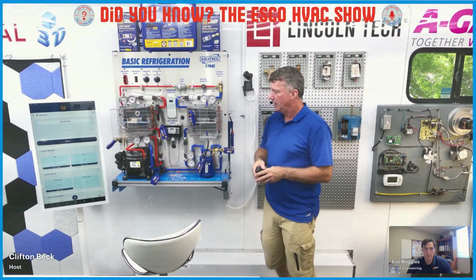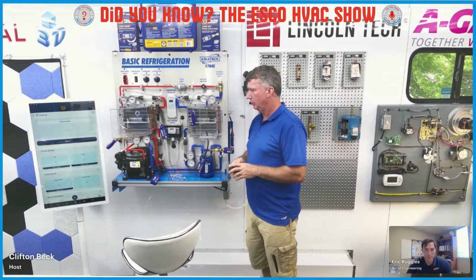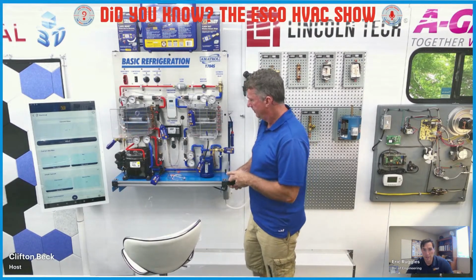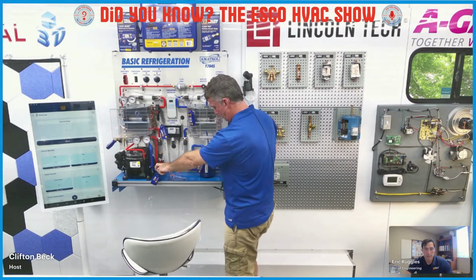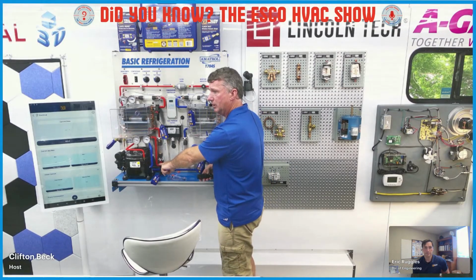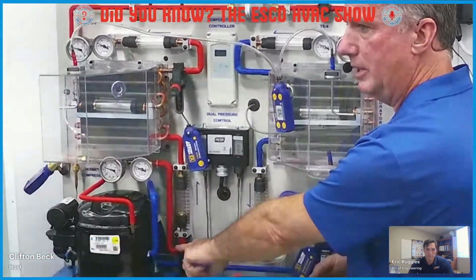Okay. So you have temperatures for the system side as well, right? So those are pipe clamps. Yep. And then again, you're going to need to put it on the low side and the high side, similar to your pressure locations. Got them right there. So here's our low side. Let me see if I can zoom into that one a little bit better for you.